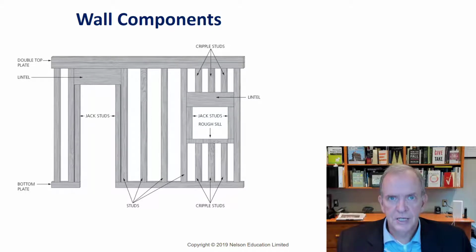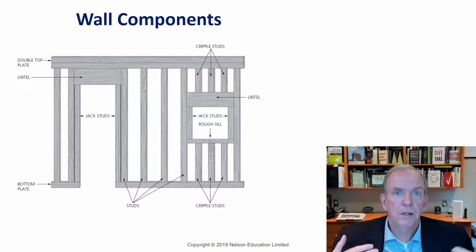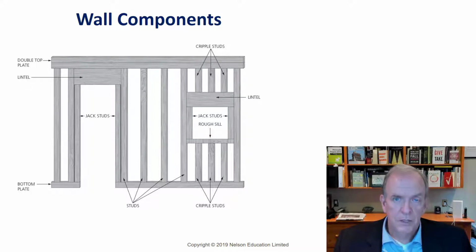So it'll be at 16 inches on center that you actually build it, because our plywood, our drywall, all of these things, they come in like 4-foot by 8-foot measurements. And that's because, quite frankly, we ship about 10 times the amount of plywood and drywall to our neighbors south of the border, and they do everything in imperial. So it makes sense that we just use the same sizes. Not that you couldn't get metric sizes, but you probably wait a long time and you pay a lot extra.